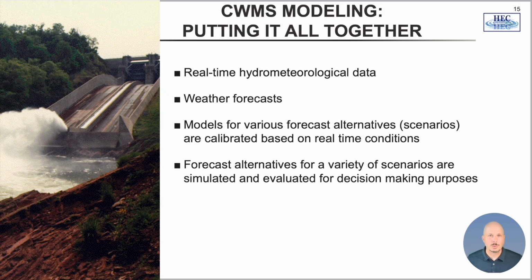To sum up, SWMS modeling relies on real-time and forecast hydrometeorological data like rain, temperature, snow, and stream flows, which are acquired, validated, and stored in a database in an automated fashion. The real-time simulation software, HEC-RTS, is the primary interface for SWMS users to access data and the integrated suite of HEC models, MetVue, HMS, ResSim, RAS, and FIA, to evaluate forecast scenarios and inform reservoir system operating decisions.